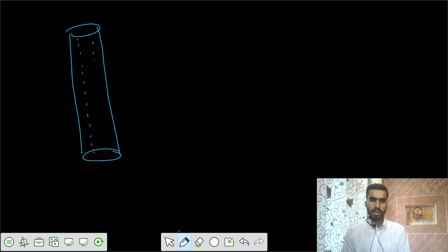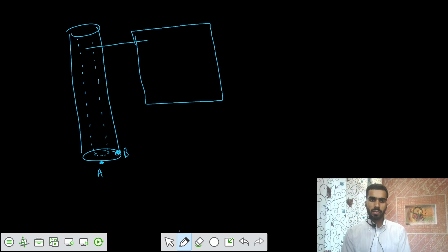There was a steel post, or we can say a pole, a hollow steel section, with a point A on the free surface and a point B. You had a signboard attached at a distance of 0.5 meter, and there is a wind pressure. So there would be some force acting on the area of that rectangle, and it would act at the centroid.